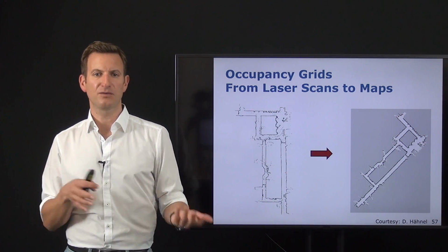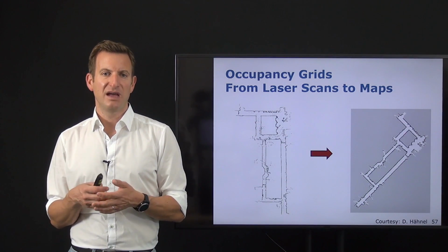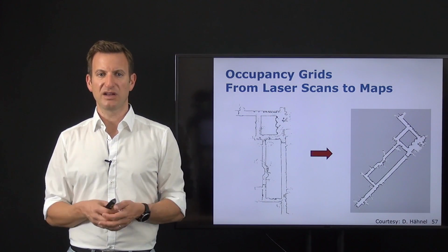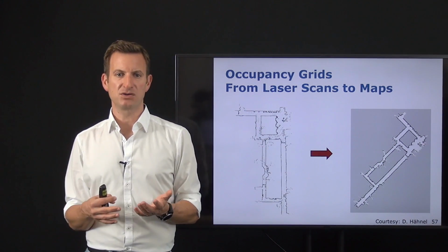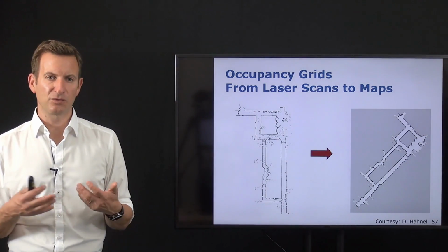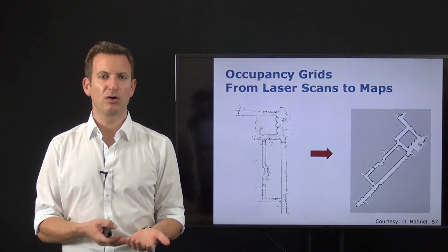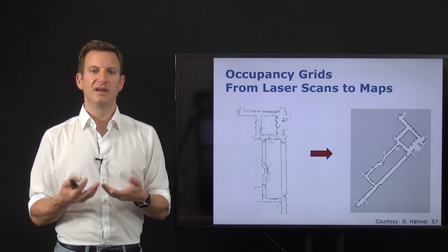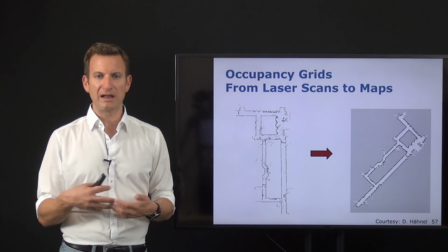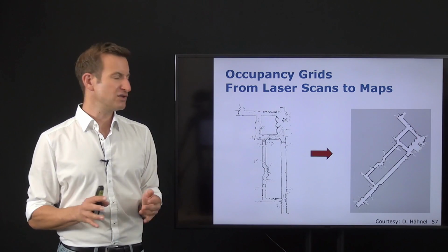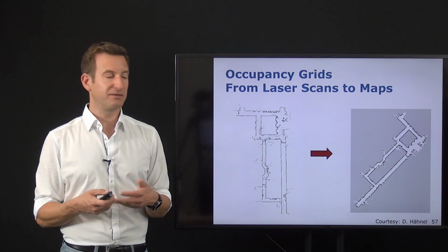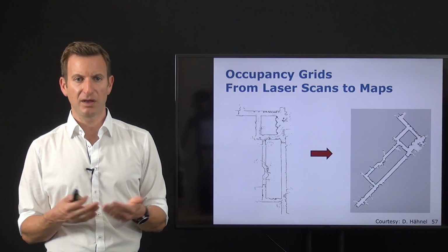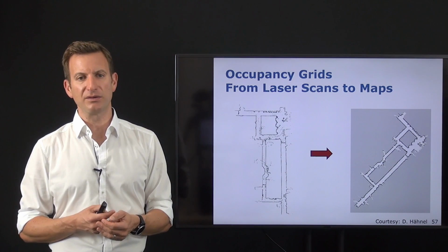And if you see it more often as free than as occupied, you basically attribute this to sensor noise rather than to the static world. But if a person was standing there for the majority of the time and then moved away just once, the robot sees the cell more often as occupied rather than free, so of course the cell would stay occupied. So it's just an effect that the static world assumption is not too bad for, let's say, quickly moving obstacles, but in general we haven't addressed the topic of dynamic objects at all in this representation, and actually are not taking it into account in the mathematical model.